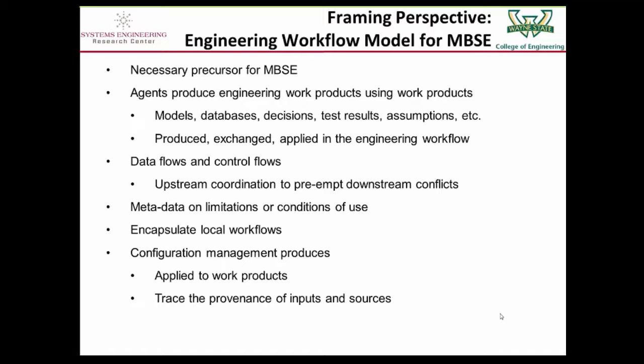And actually, we're doing even more, which is that we won't talk about, say, density over the entire ship. If we've got a compartmented design of the ship, we can talk about the density, energy density, information density, et cetera, of each compartment. In ground vehicles, we often divide the compartments based on the motion relative to each other, or isolation from some factor like noxious exhaust or whatnot. So once we end up with these kinds of compartments, if that's the basis for the architecture design, we can talk about the various densities that we're trying to pack in.